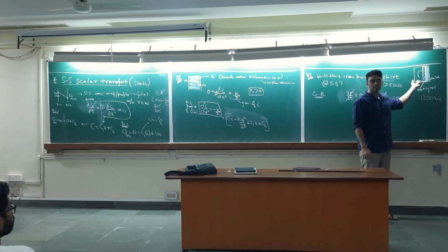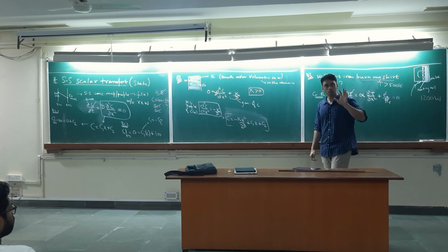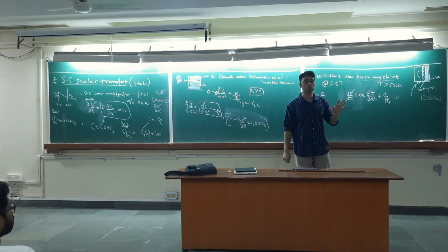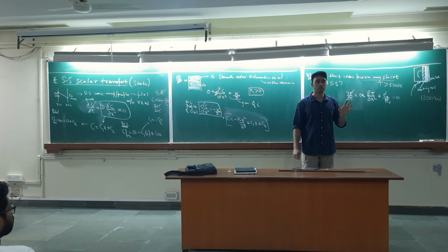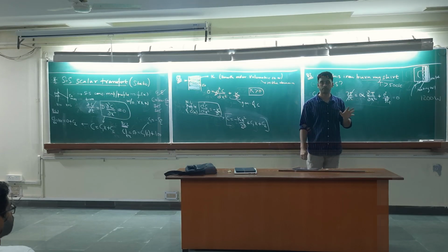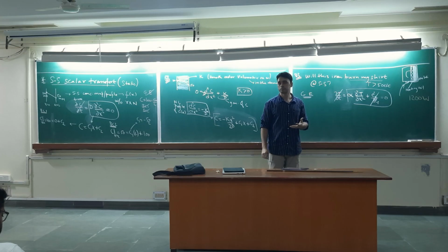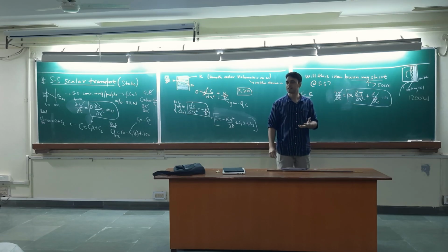The heat is generated in the heating coil, which is outside the domain. So power is being provided, but through the domain or through the boundary? Through the boundary, right? So the steady state profile is going to be linear or non-linear? It will be linear.